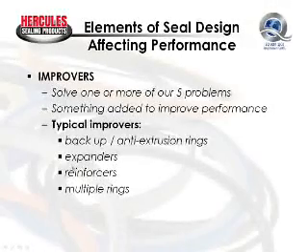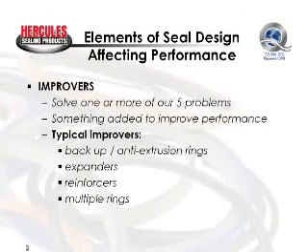Reinforcers. A typical reinforcer, if you think about V-packing, you have homogeneous rubber rings, and then you have neofab rings. The neofab rings are a neoprene cotton fabric material that are coated with rubber that enables the V-ring to be used at higher pressures. And then multiple rings would be examples of improvers. These would be redundant sealing. Okay, one type of multiple ring could be a V-packing.